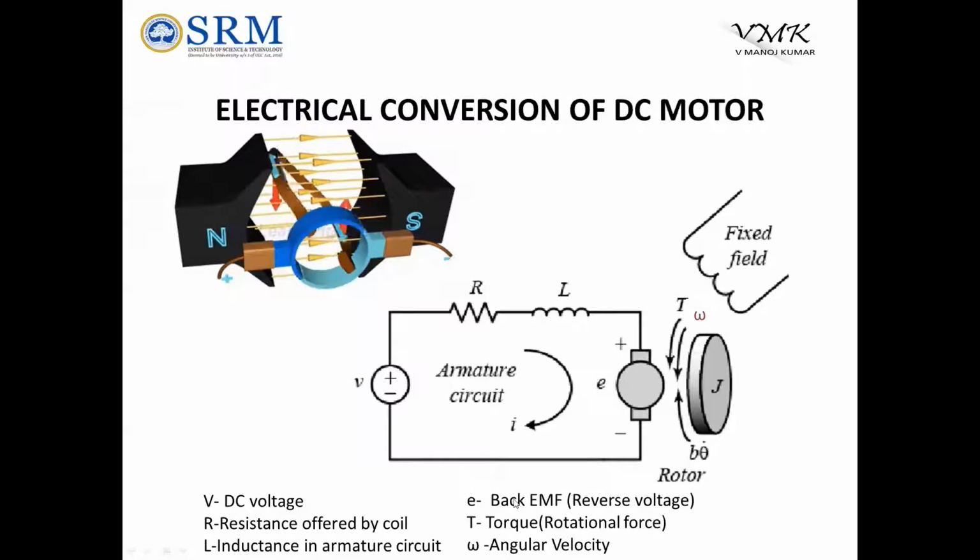And one more term is called back EMF. What is the back EMF? That is called reverse voltage. See here, whenever this motor is rotating, this shaft is also rotating. What will happen? This is going to cut the magnetic coil, so a small amount of reverse voltage will be generated. This is the principle of